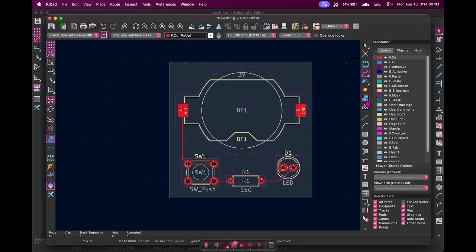Oh my gosh, bro. All right, so you're going to click this button. If you hover over it, it's called drop. No, don't. We're not placing vias just yet. It's option Z for my MacBook. I don't know what it is for you weird Windows users. Just click this button, draw filled zones, and then you're going to draw it around, outside of the edge, like this rectangle. Don't draw it inside. Don't draw it on the line. You're going to draw outside of the line. You don't have to make it super big, just right above it.